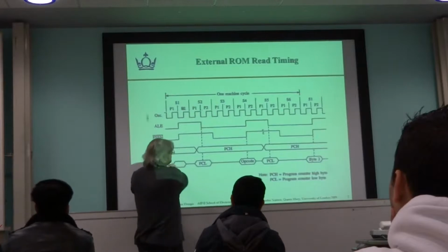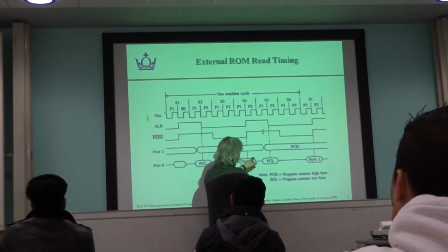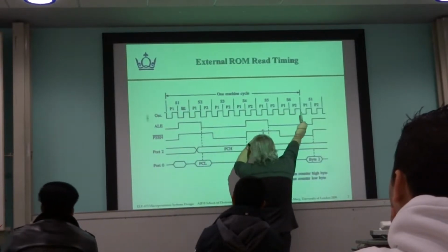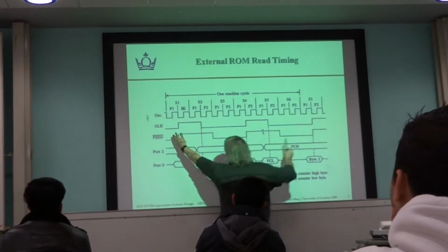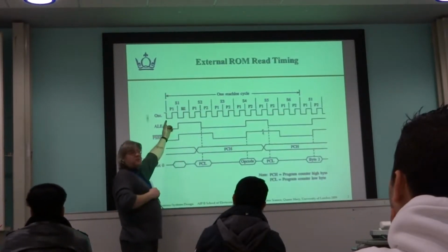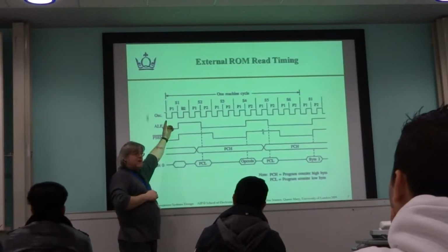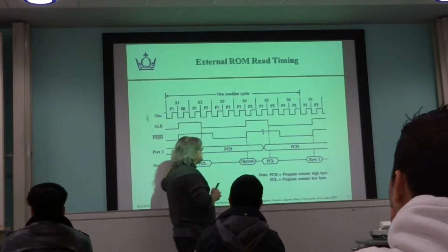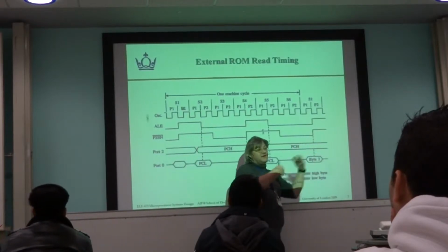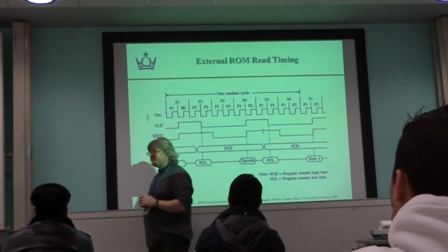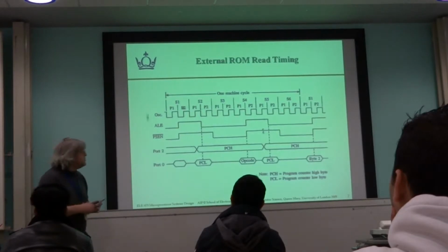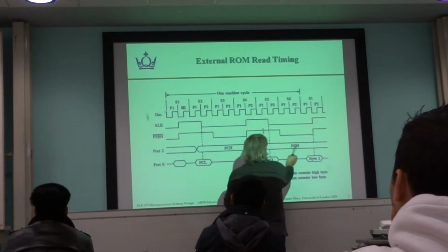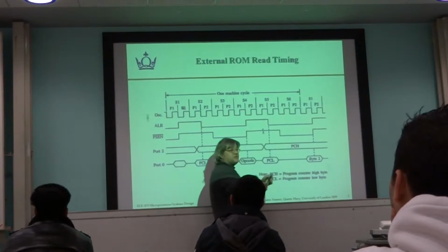By the time it's done this, there's a few more bits and pieces here, but generally speaking, to complete that whole cycle, the oscillators had to go up and down 12 times. So it's taken 12 clock cycles to effectively bring the instruction in from the outside world and execute it. During this last phase here, this is where the instruction will be interpreted and some action will be taken.